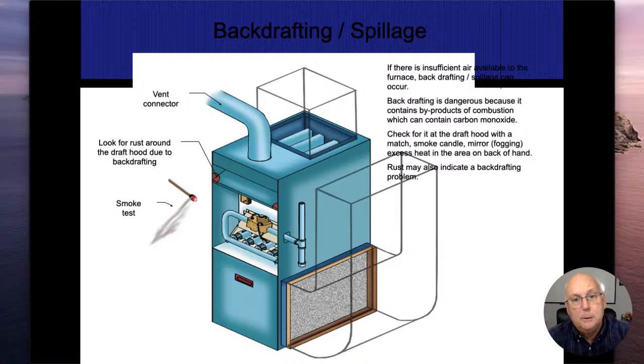All right. So here we have our burners. This is where our combustion air goes in. Our dilution air comes in at the draft hood. So our flame goes in here. We create our bad gases inside the heat exchangers. They group up again and send those bad gases up and out the vent. I have to mix dilution air in with it in order to clean it up, basically, or cool the temperature down so it doesn't move too fast.